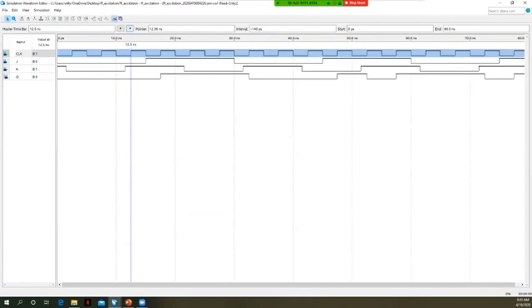Had it been 1, it would transition to 0 at this point. Let's go here. Next rising clock edge, J and K are both 1s. That's the toggle state. Since Q was a 0 in the previous state, we could see that Q now toggles to 1. Next rising clock edge, K is a 0, J is a 1. That's the set state, so Q remains a 1.